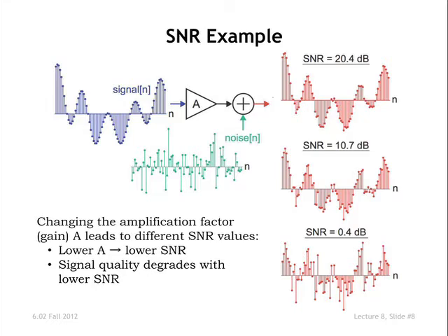So what I expect to see is perturbations of the original signal that are comparable with the signal values themselves. And that's sort of what we see here. The shape of the signal is pretty distorted at this point because the typical amplitude of a noise sample is comparable with the signal sample that I'm interested in. Okay, so when you get to 0 dB, you're starting to get quite disturbed looking waveforms.